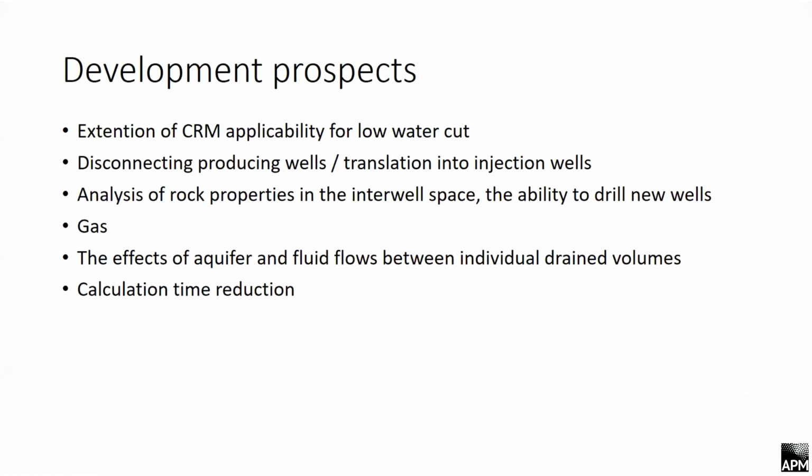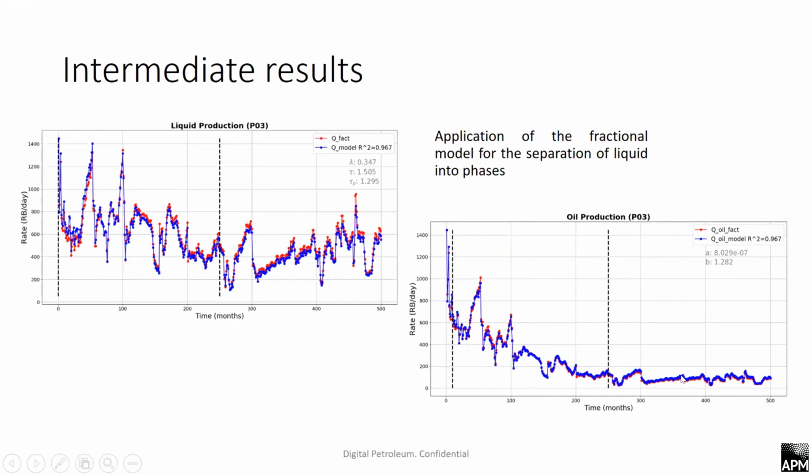Okay, yeah, Maxim. One question: why is your approach not applicable for low water cut? As I see in your models and your mathematics, there is no limitation for low water cut. Yes, but since these cases were quite simple, we performed the match procedure quite well on the low water cut. But in general, CRM is useful for steady state regime where water cut is high enough. I mean, it's inappropriate for unsteady mode on the first stages.